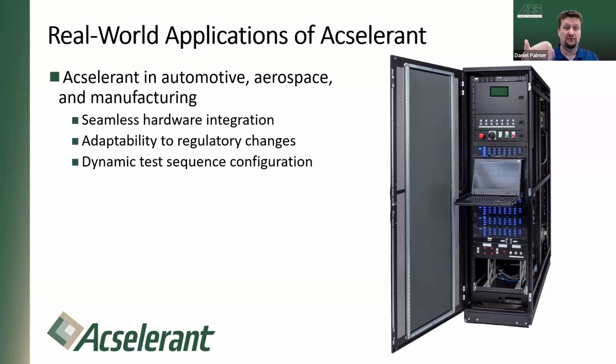Then as they developed and further progressed the program and got into the actual physical control modules, those were installed. Just through changing some simple routing, we were able to take those control modules and hook them up to the same physical I/O, the same communication buses. So it was a seamless switch between running a model-based system and an actual physical HCM, which allowed them to do all their testing and integration with the rest of the aircraft.